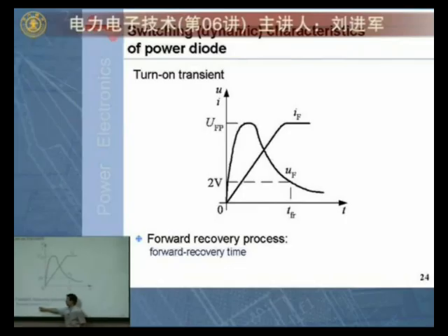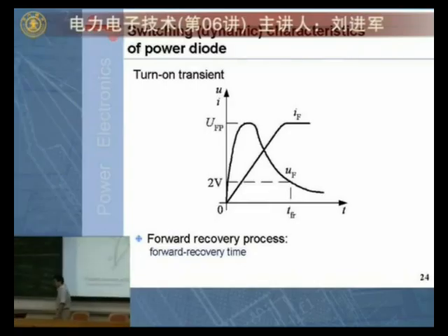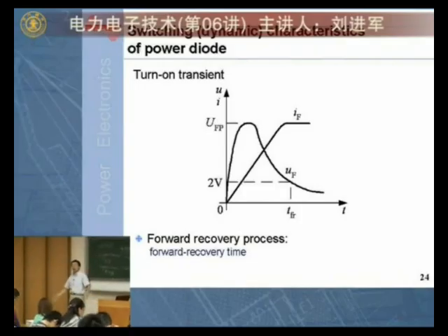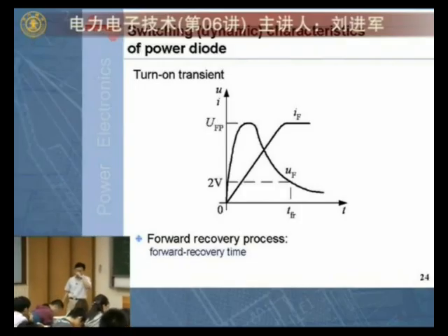Actually, this forward recovery time is much shorter than reverse recovery. So usually when you use a diode, you seldom care about forward recovery. Usually you care about reverse recovery because reverse recovery time is much longer than forward recovery.